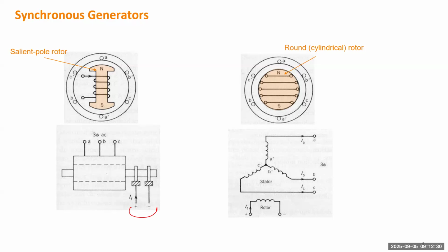When the rotor is revolving, we usually consider the counterclockwise direction to be the positive direction. The magnetic field will have flux cutting the armature windings, winding A, winding B, and winding C. So there will be current and voltage induced in each winding, to power the external system.